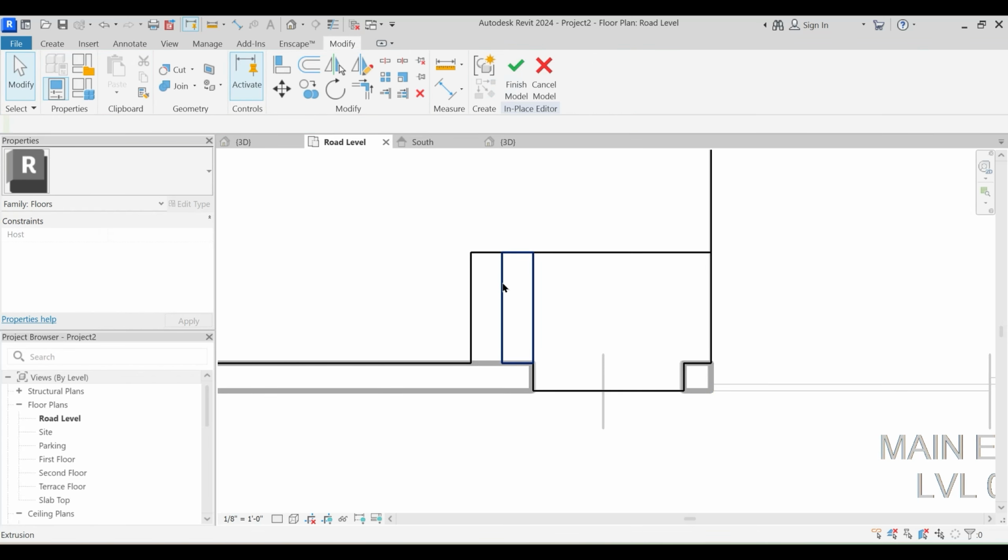Architecture and ramp 2, edit type, solid, 10 feet maximum incline length. Okay, 5.5 run. And from here to here, and let's just create with this first, and let's see whether it's been created. Yeah, fine, perfect, no issues. Okay, so see, this particular ramp is going from 0 level up to 2 feet. There's a little bit of small glitch here, but that's okay, fine.